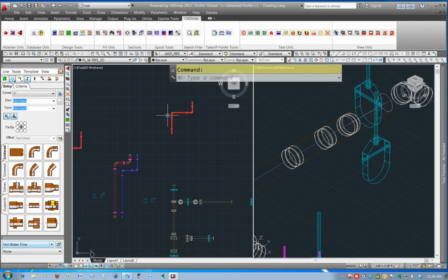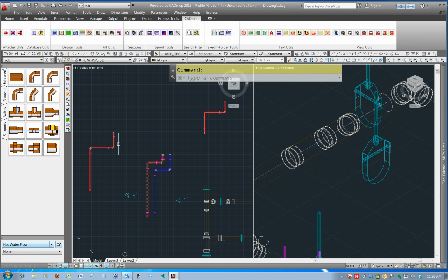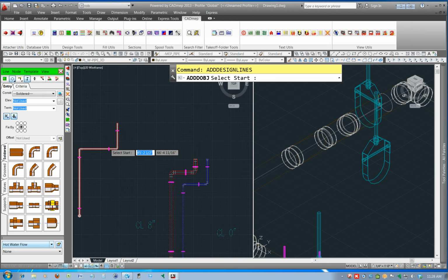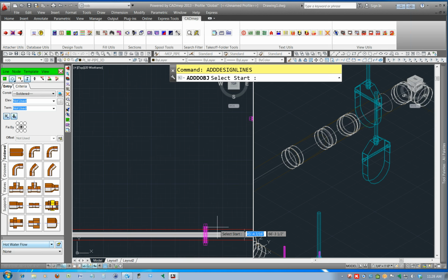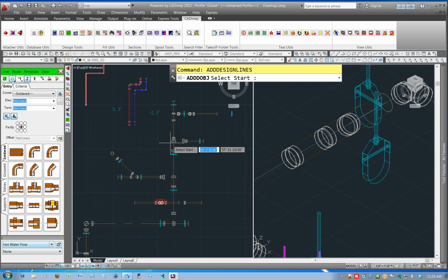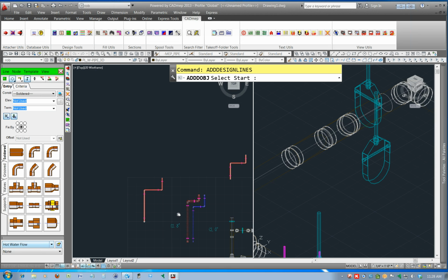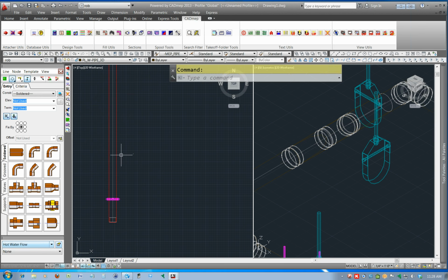You have to close out of that design line and then hit the new design line button. You see how they went gray? The design line went gray, and that lets you know it's turned off. I'm zooming around too fast because of the remote connection. Now you draw another design line, and you're okay. Oh, I didn't pick a size, but you get the idea.